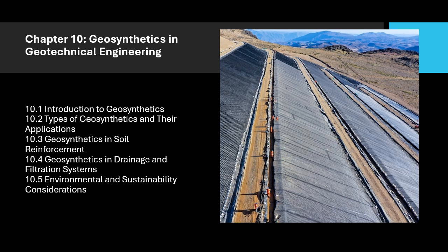Applications. Geocells are used for stabilizing soft and weak soils, slope stabilization, erosion control, and foundation reinforcement in various civil engineering projects. Benefits. Geocells prevent soil erosion, improve compaction, and reduce differential settlement by distributing the applied load over a wider area. 4. Geocomposites.